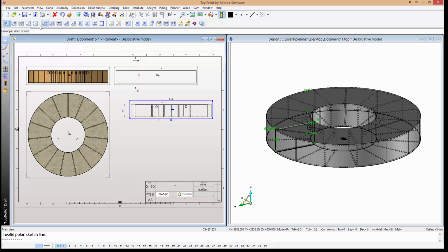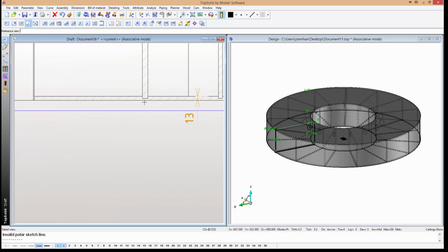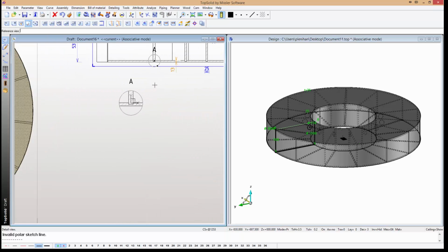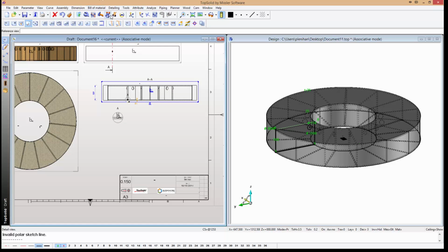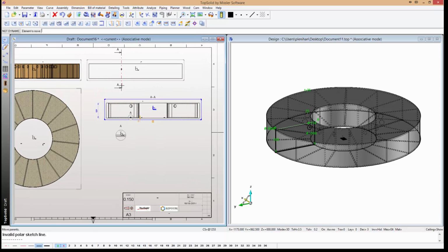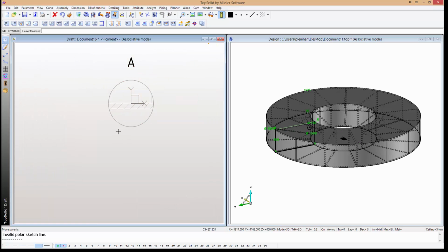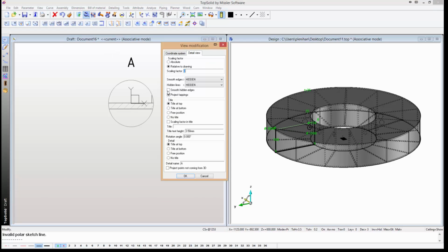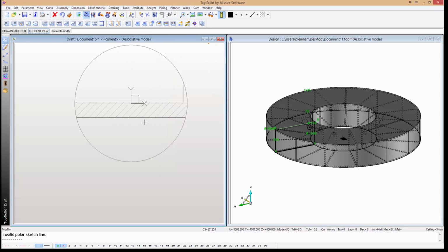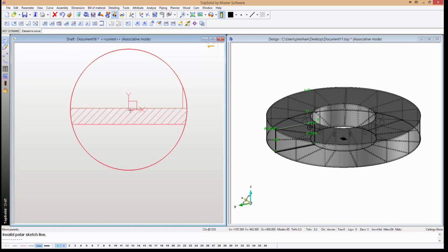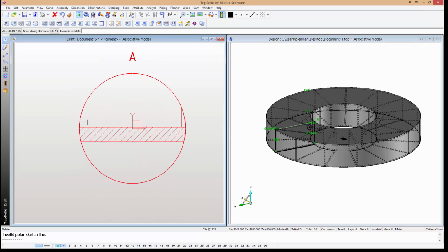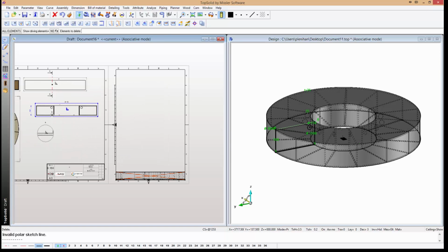Let's go into this drawing here and let's create a detail. I want to create a detail here. Say our drawing, circle, maybe from here, extend it out, bring it up. Now, what we can very easily do, if we said, right, let's move this, maybe to this distance, it updates my drawing to suit my new section. Do you see that? It's updating. What I've also got here is I can blow this up to whatever size I want, maybe 5, move it out.